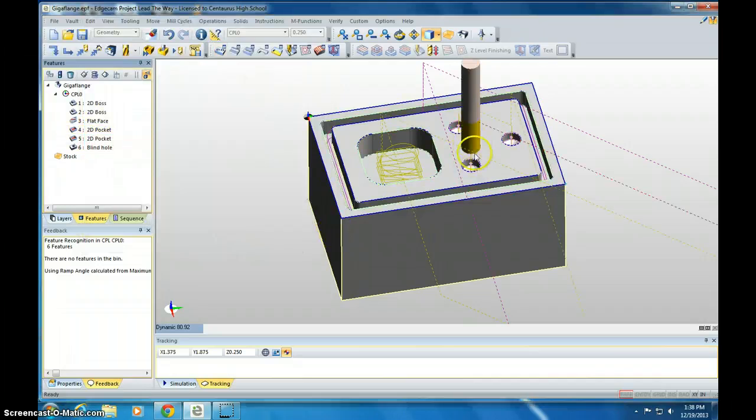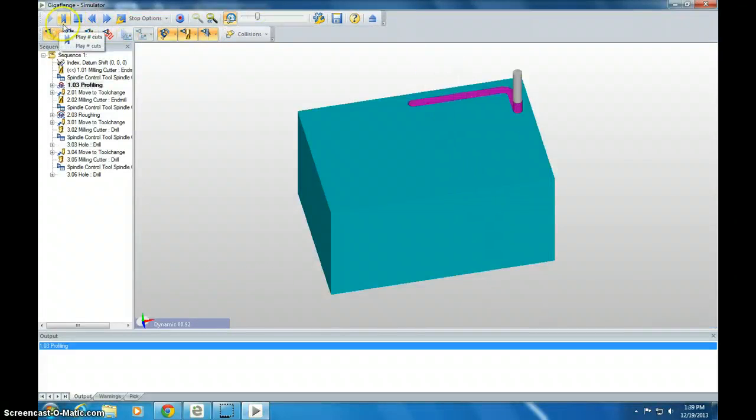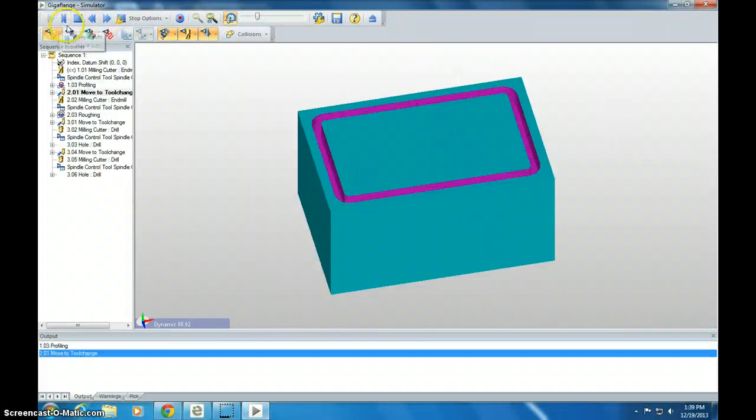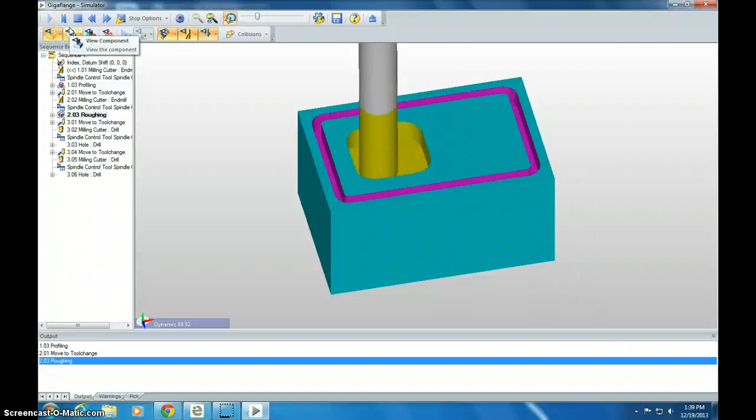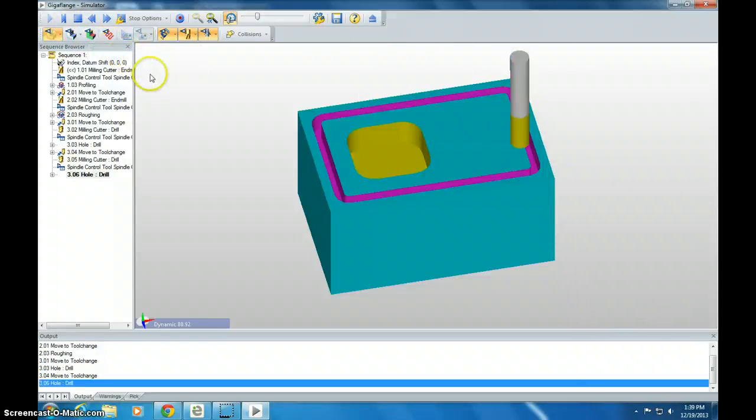And you can see this tool comes in. So we have all the tools coming in and milling, and let's preview this. So if you click up here, simulate machining, click that, and I'm going to slow this down a little bit and click play, and you can see it profiles first twice around to get both depths, and then it mills out with the 1/2 inch bit, and the 1/4 inch drills all of them into there.